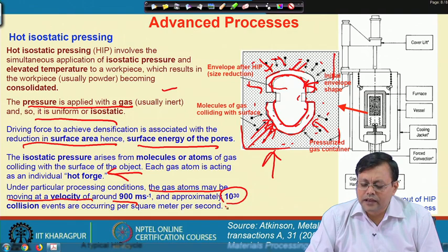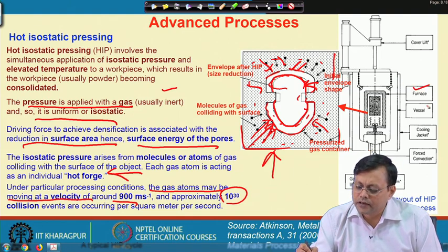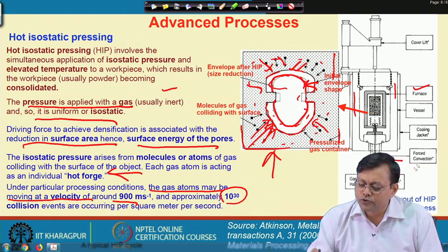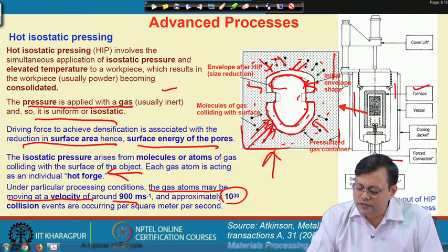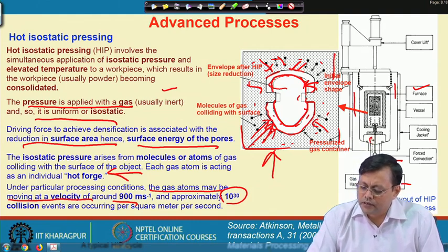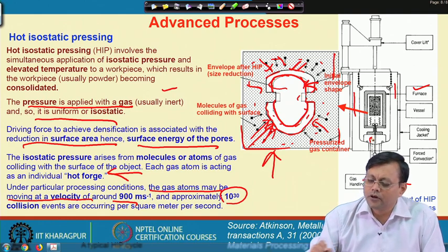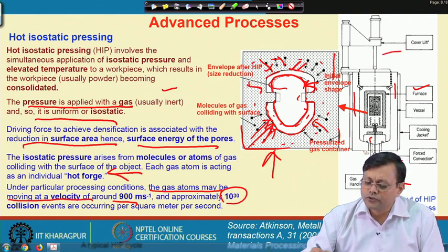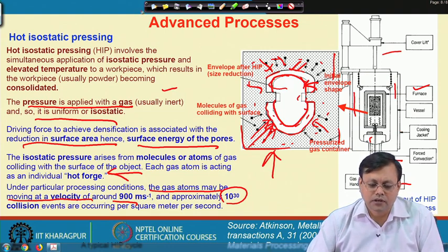That basically assists in getting a very high compact density. A schematic of such a hot isostatic pressing chamber is shown here, with a furnace. This is a furnace that provides the heat. We may need the assistance of forced convection or not, that completely depends on the user's choice. However, for gas handling we may need some vacuum. So, initially we put some vacuum and then we put some inert gas inside, and some electrical circuits are there. This is just a layout of the cover lid and so on. So, this is the total schematic of such a hot isostatic press.